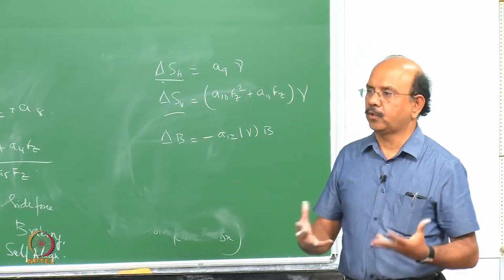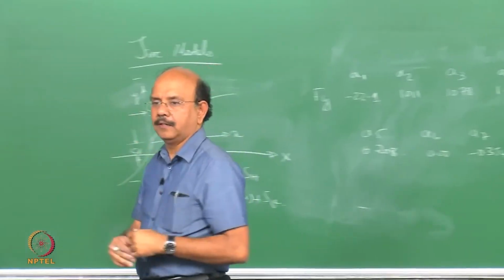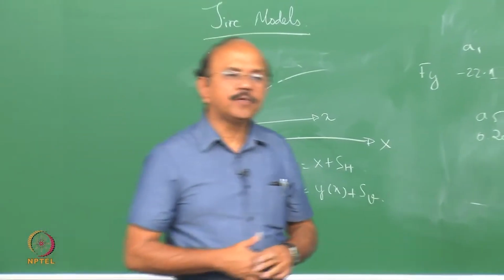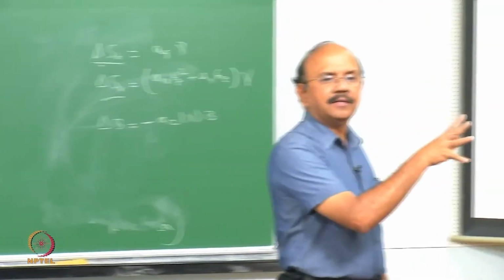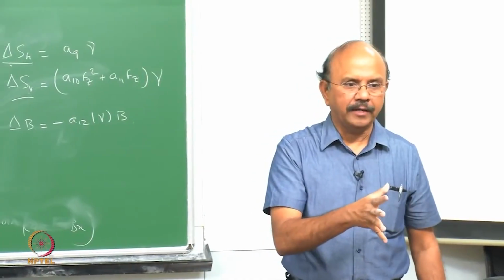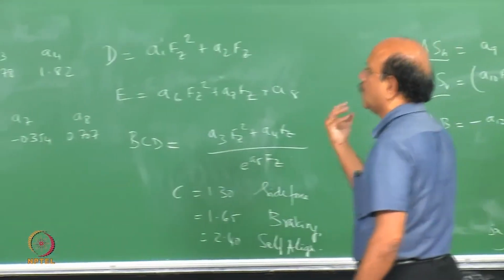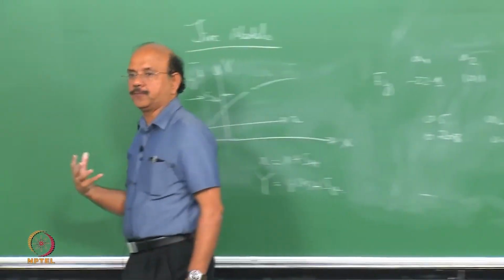They have a machine with a surface on which the tire is mounted, and they have a facility to measure these forces and the slip angle and so on, and they determine this in the laboratory. There your question of surface becomes important, because the question is how do you characterize mu? So the surface becomes important.